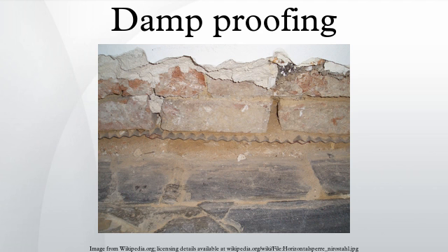Remedial damp proofing. Until the 20th century, masonry buildings in Europe and North America were generally constructed from highly permeable materials such as stone and lime-based mortars and renders covered with soft water-based paints, which all allowed damp to diffuse into the air without damage. The later application of impermeable materials which prevent the natural dispersion of damp, such as tiles, linoleum,